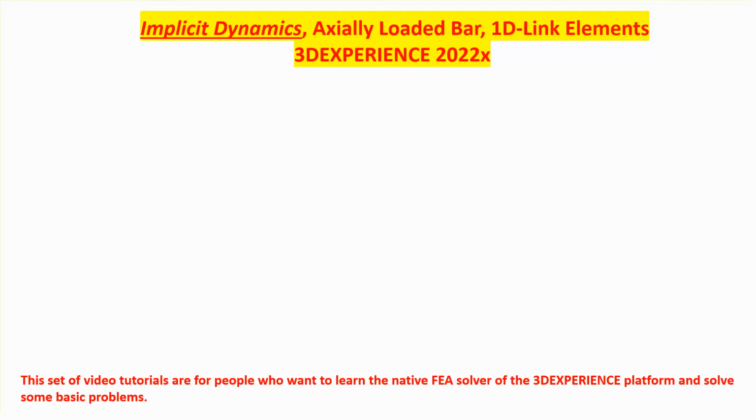Now, let me remind you that modal dynamics applies only to linear problems. So if you have a problem that is not linear, or perhaps you don't have an idea of how many modes you have to take, etc., you can probably use the implicit dynamics step more intelligently.